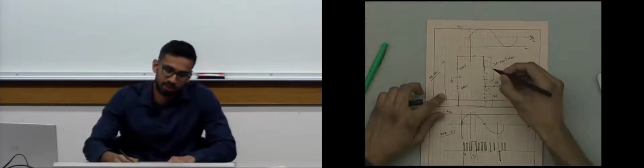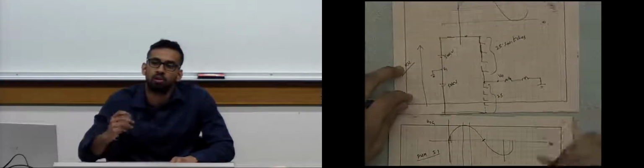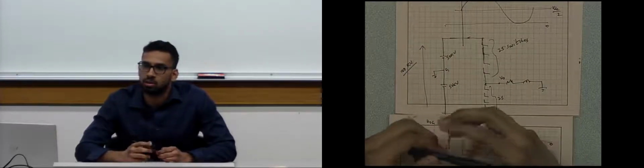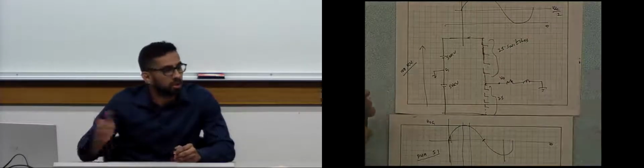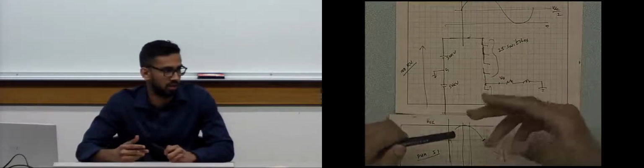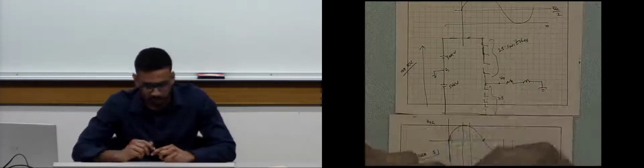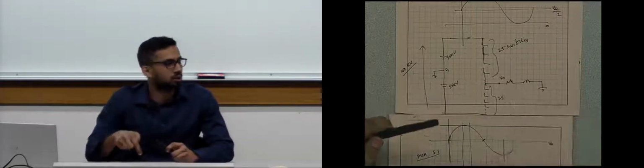And the other problem is these 25 switches in series may not have the same on-state resistance. So the blocking of the voltage will not be even. Some switch may see 6 kV, some switch may see 4 kV, so then we need more switches than the maximum 4 kV for it not to fail if the resistances are different and voltage sharing is uneven. So we need additional voltage sharing circuits for these series connected switches.